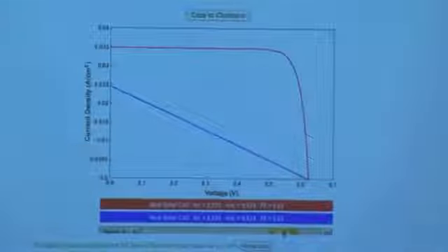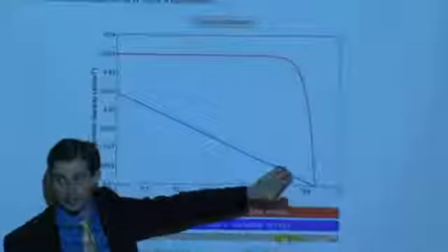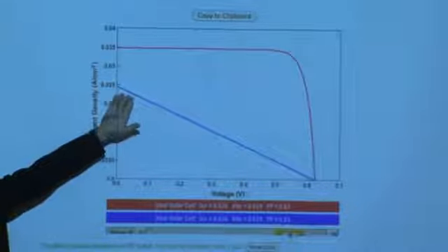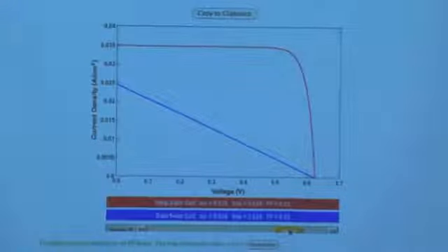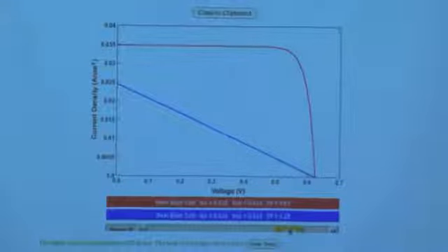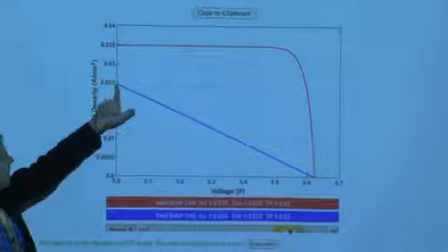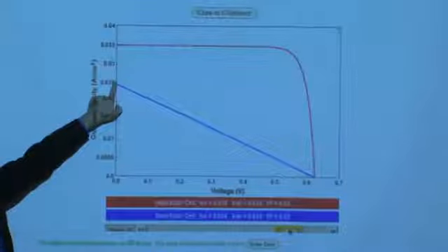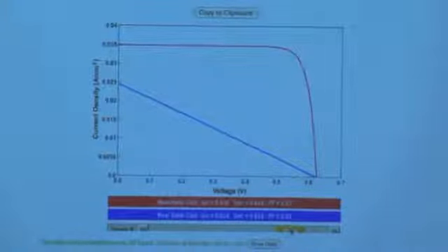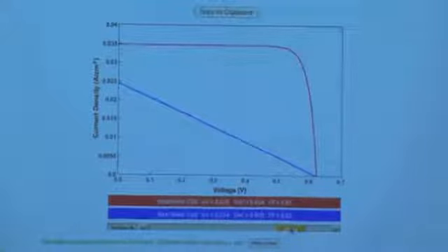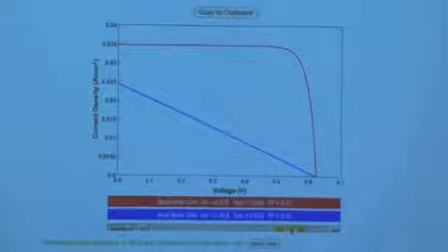So if you were to do an extreme condition, you might have so much series resistance that your IV curve looks like a straight line. You have an ohmic resistor now. The resistance component is swamping out any diode-like behavior of your solar cell. And that's why you have a line. Likewise, you're dropping the total current output of your device, right? Because you have a resistor in series now preventing the current flow. OK, so that's, again, an extreme case of what can happen.